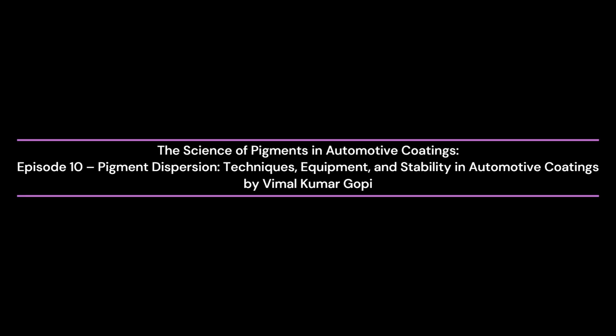Rheology is also impacted by dispersion. A well-dispersed pigment system exhibits predictable viscosity, flow, and leveling properties. Poorly dispersed pigments can lead to viscosity spikes, shear thinning or shear thickening behavior, and uneven film thickness during application. High-quality dispersion ensures consistent spraying, brushing, or rolling behavior, reducing defects such as sagging, orange peel, or uneven coverage.